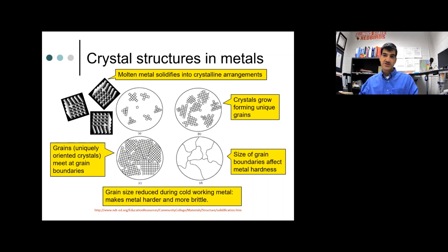So the dislocations that you might get along slippage planes have a really hard time going from this grain into this grain, because the slippage planes are at different orientations. So these grains and the grain structures have a really important role to play in determining the mechanical properties of materials. We will talk more about that in the heat treatment section of this class in a month or 2.